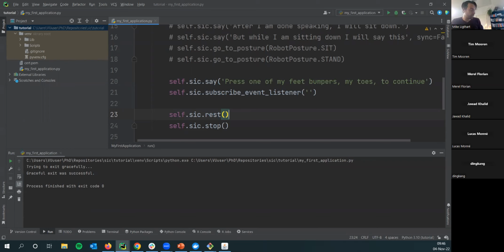Why is this important? Because maybe you will notice, or you've already noticed when using this robot the past week, that its motors are prone to overheating. It will turn off these motors sometimes when it does so, and then you have to wait until it's cooled down before you can use it again. But in the long run, this actually damages the robot.